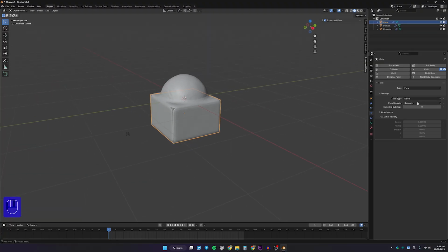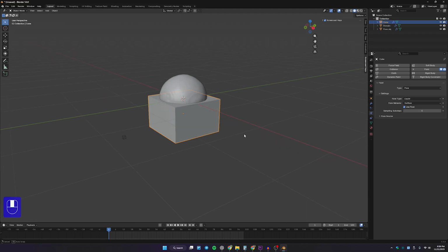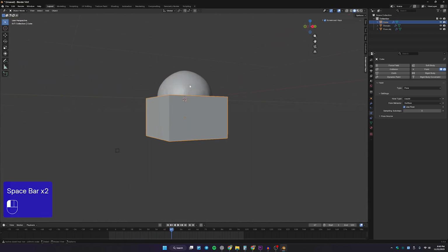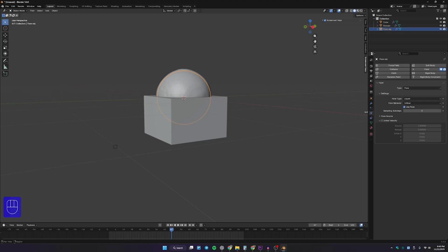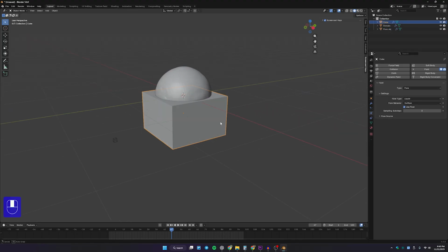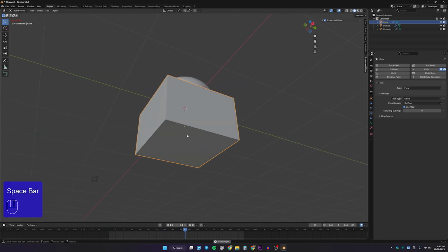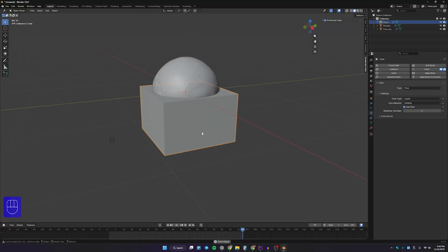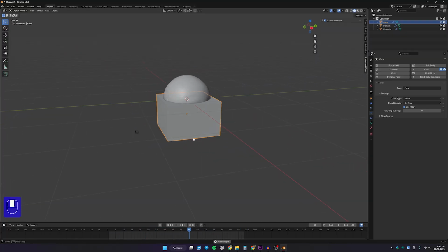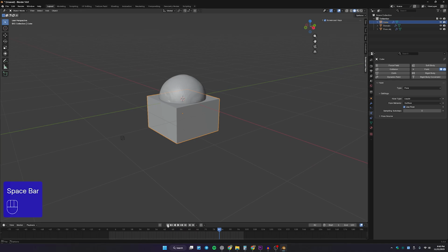So I'm going to change my flow behavior to outflow. Right now you can see if I play this, my liquid is supposed to be filling, and it's supposed to be creating liquid continually because my flow object type is inflow. But since my outflow object is right beneath that object, it destroys or deletes the particles of the liquid. So that's why you can see there is no liquid coming out of this surface. It is continually creating, but the outflow object is continually deleting my particles. Right, so I think you got that one too.